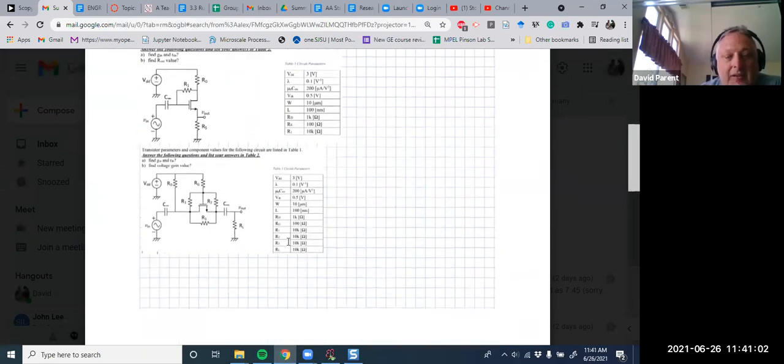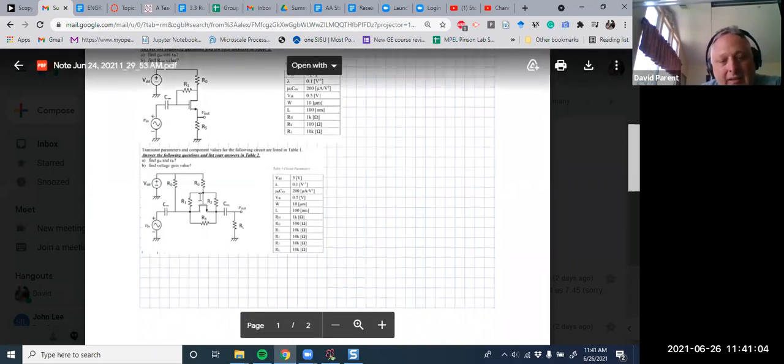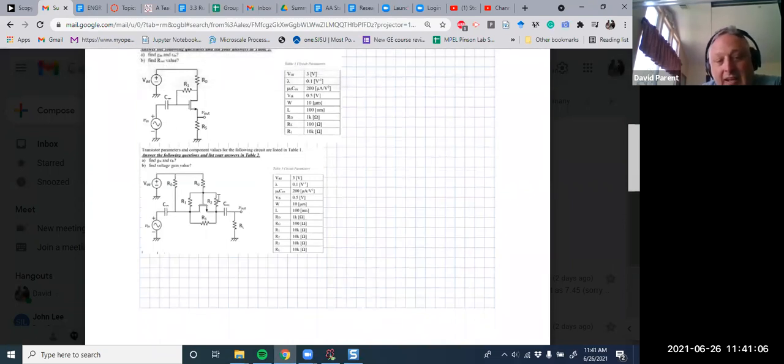to here, let's look at this problem. Let's look at it at DC. Infinite capacitance. At DC, the impedance of a capacitor is infinite. So in fact, you take it out, it's not there. And so I have a voltage supply, and it's tied to ground, but there's no path to ground.